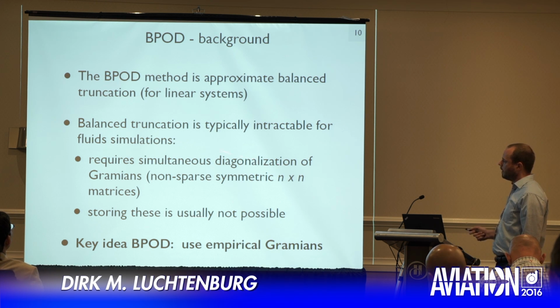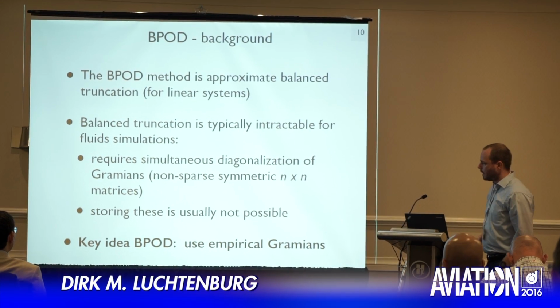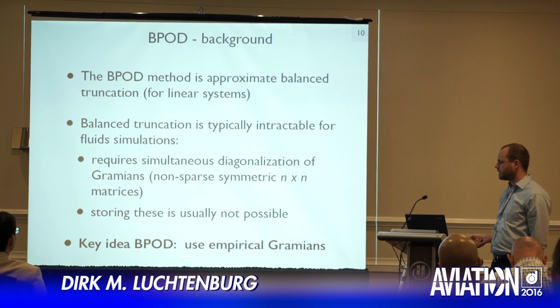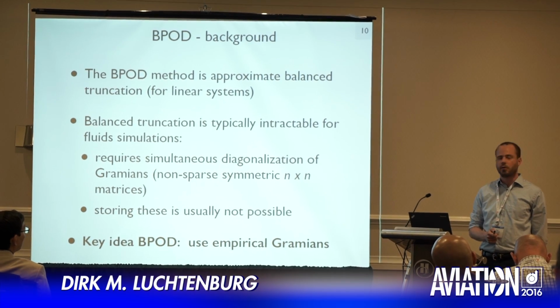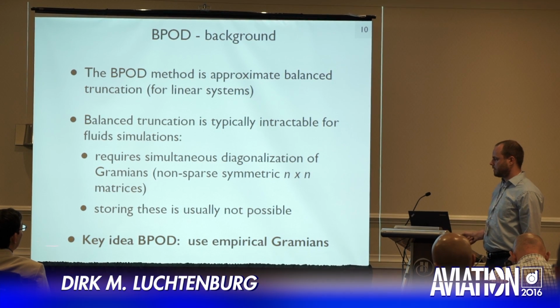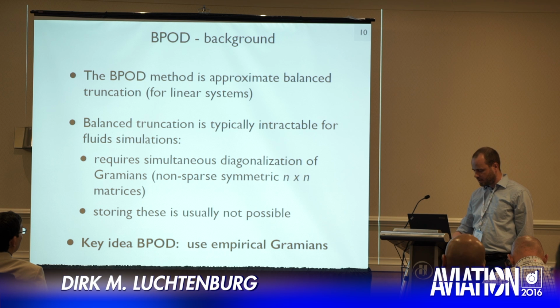You have to solve Lyapunov equations and compute gramians, and that turns out to be a very big problem to solve. So what BPOD does, it basically makes this balanced truncation possible by using so-called empirical gramians. So instead of solving for big matrices, now we're going to be using empirical gramians, which are composed of snapshots.